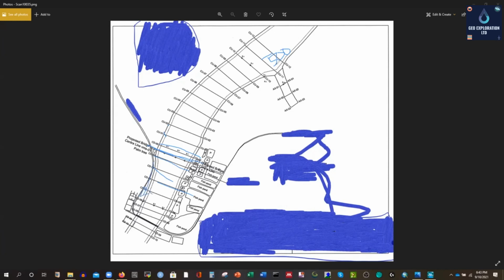But in the model, you can import these cross sections, or you can create the cross sections from upstream to downstream. We'll do that. We'll start the cross sections from upstream to downstream, and the upstream cross section number will be the higher number, and the downstream cross section number will be lower. So that will automatically be fixed. If you provide two numbers, 1 and 2, then 1 will be the downstream and 2 will be upstream. So that is the notation. The modeling software HEC-RAS will automatically understand that the minimum value is the downstream cross section, and the maximum value is the most upstream cross section.